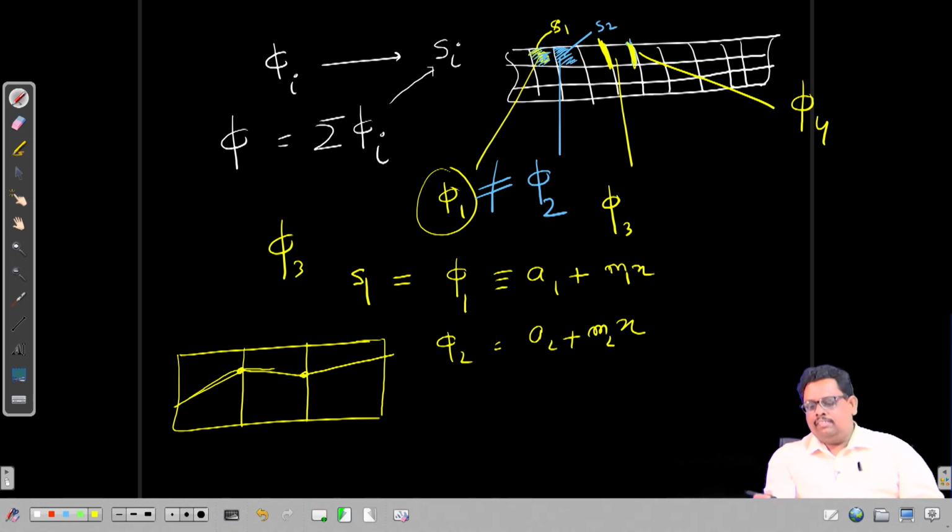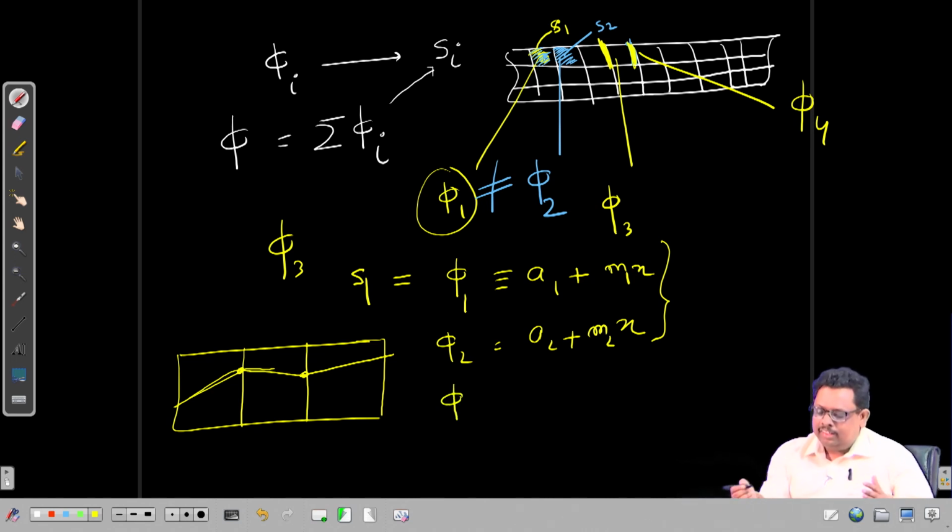Okay. So, this is also considered a lower order panel method, when we can assume phi is constant or we can assume phi is linear. Now, suppose you are still not happy and you say that no, I want this phi to be a quadratic function. So, it should be some a x square plus b x plus c, something like this.